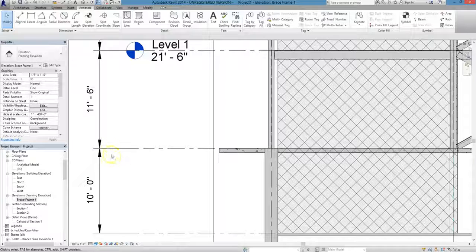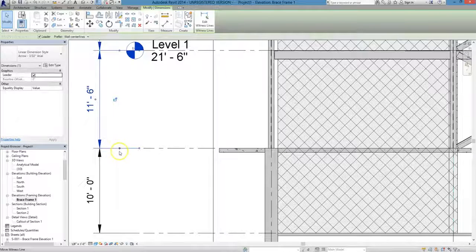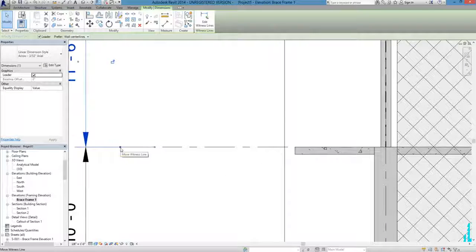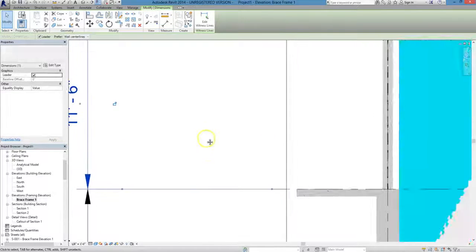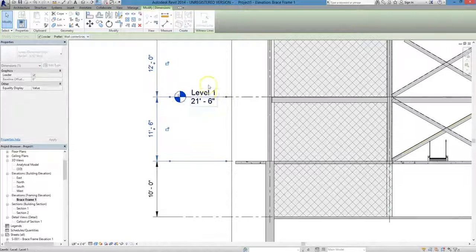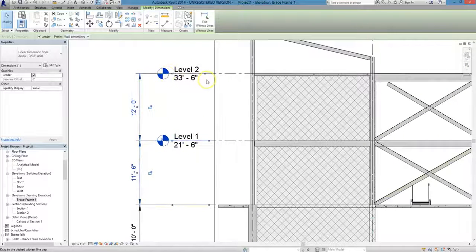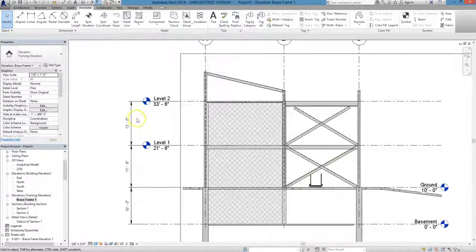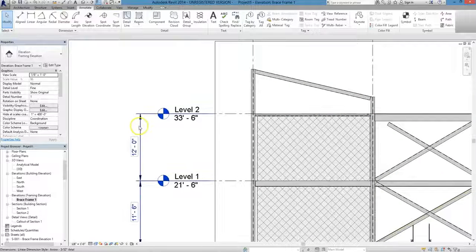You can also control the shape of the witness lines. That is, the line that shows what the dimension refers to on your project. If you zoom in to the line that currently is at each level, you'll see these little nodes. The left one is called the witness line, and you can move that around. The node on the right lets you control how long the endpoint of the line is before it reaches the witness line. So feel free to play around and adjust these as much as you need, or as far as seems appropriate for the scope of your project.